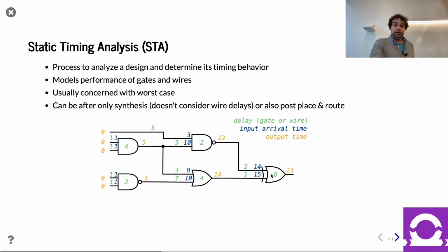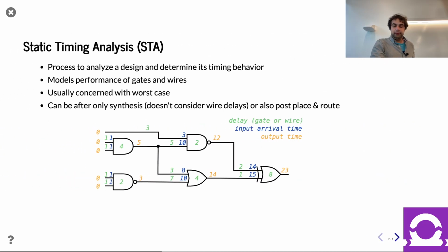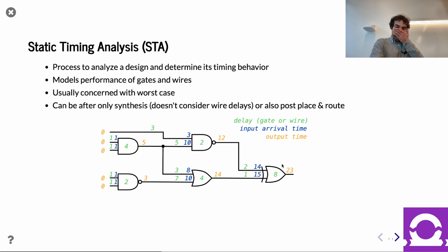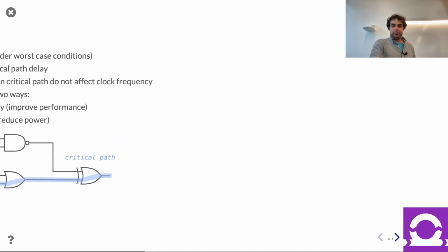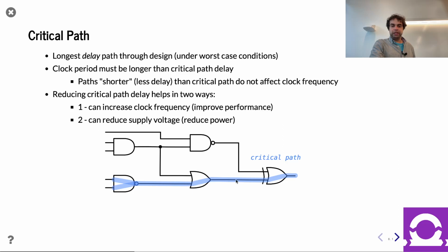So you can trace backwards, picking the largest arrival at each step of the way to see what the critical path is. And if you do that, going backwards, we say, oh yeah, this one is the latest input. This is the latest input. So going back to the prior slide, the one I showed does show the critical path, right?